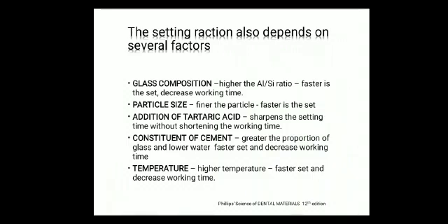If tartaric acid is more added, it sharpens the setting time without shortening the working time. The constituents of cement: greater the proportion of glass and lower the water, faster the set and decreases the working time. Temperature: higher the temperature, faster is the set and decreasing the working time.